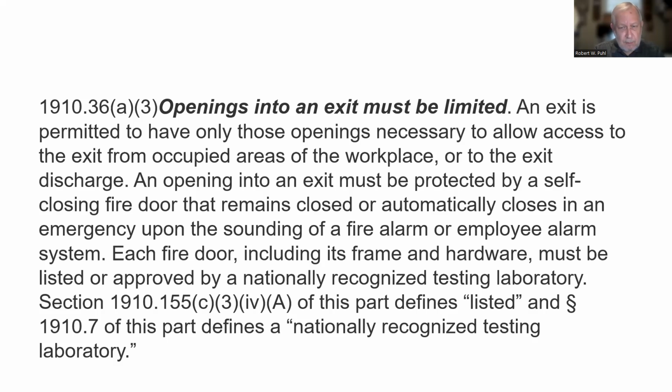Each fire door, including its frame and hardware, must be listed or approved by a nationally recognized testing laboratory. Section 1910.155(c)(3)(iv)(A) of this part defines listed, and section 1910.7 of this part defines a nationally recognized testing laboratory. Don't you just love it when OSHA throws you off into not just one standard, but 2 different standards for a definition?